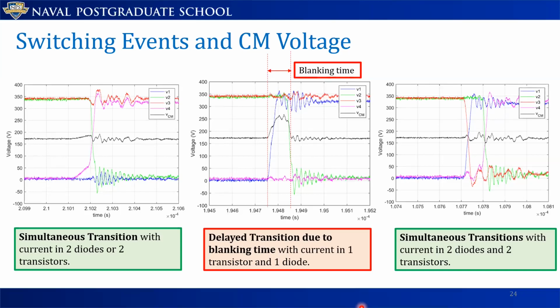Typically, they are connected in the sense that if you have a high frequency conducted emission on a ground wire, for example, then if the wire is long enough or is placed in the wrong place, that can cause radiated emission. So yes, in general, yes. Now, in a specific case, there are also other forms of radiated emissions, not just the ones produced by the current flowing on conductors. But for those, for sure, yes.